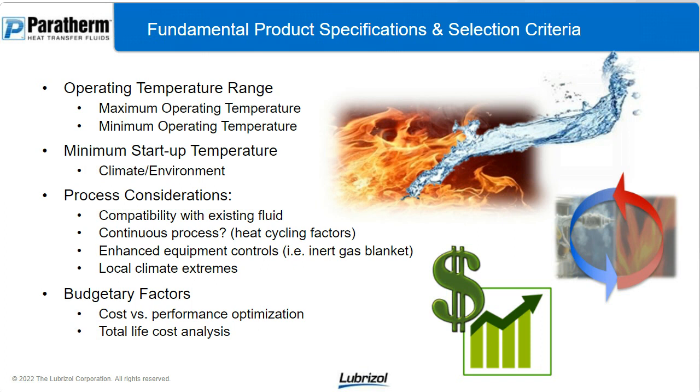Make sure that the fluid also can be pumped and efficiently heated at whatever the minimum startup temperature is going to be. That's all going to be listed in the product literature if you're dealing with a legitimate product. Process considerations. If you have an existing fluid system, or an existing system that you might have drained out and are refilling, you want to make sure that you're not putting in a product incompatible with what was there before, or that your materials of construction are compatible. Okay, you never want to put water into an oil-based system, for instance. But also, you might not want to mix synthetics with mineral oil-based products. You really need to take that into account and talk to your fluid supplier before you make that decision.